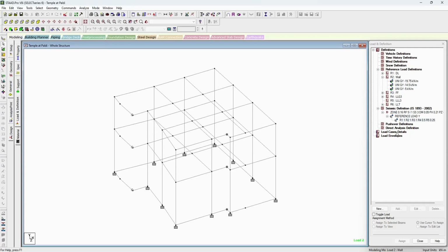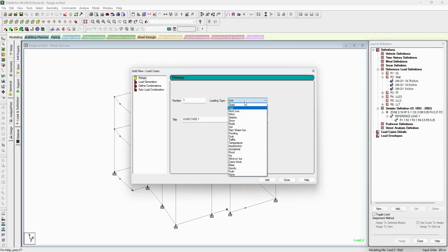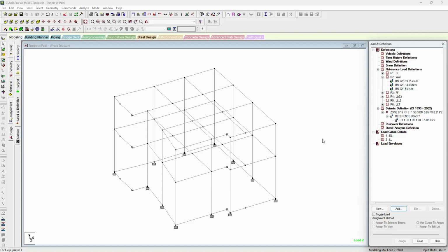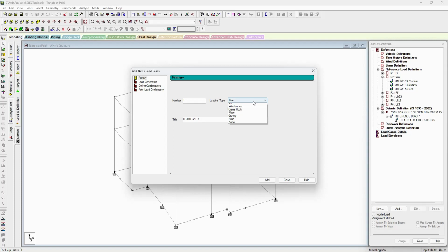Now you have to create the actual primary load cases and combinations. So select the load case details, press add, and create dead load with the extension DL. Create live load by saying LL. Oops, we have made a mistake. The seismic loads need to be at the first level, then all the other loads. So we are deleting these loads. We are creating the seismic load first.